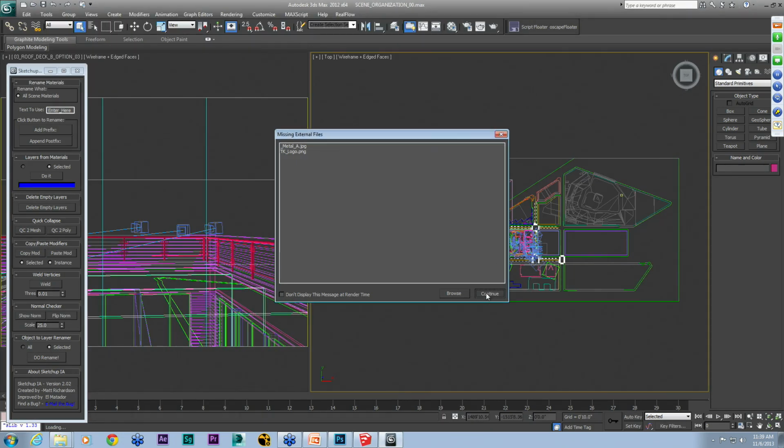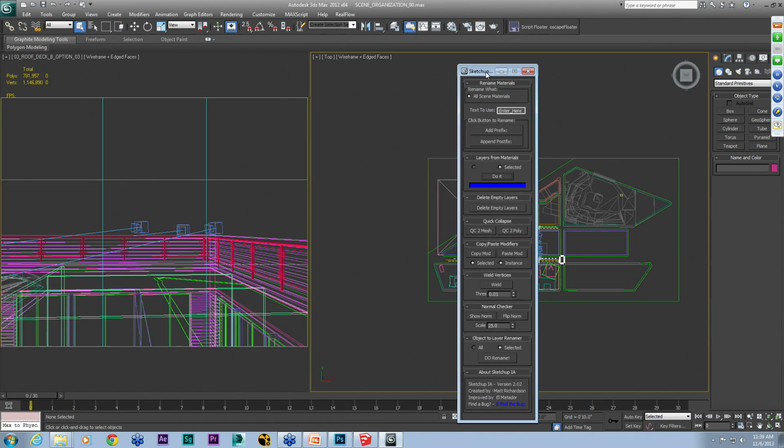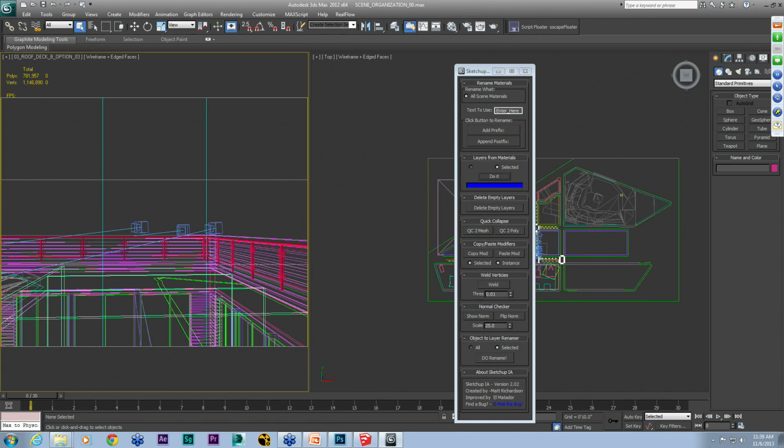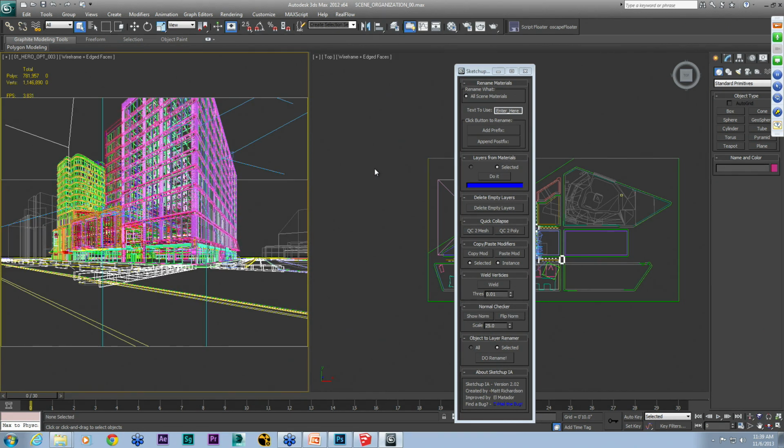I know the direct import preserves component hierarchies and all those different things, so that can also be advantageous if that's the way you're familiar with working. But just for us here, it's easier to get it out into those materials. We definitely have to do that extra step to go to V-Ray. Yeah, if we're just doing quick mental ray exteriors, that's the gateway to do it. But I feel like the 3ds way, by material, is easier for V-Ray.